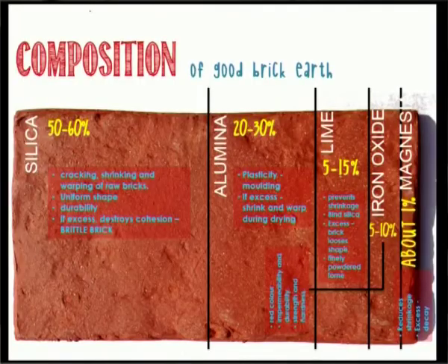If it is in lumps, when you burn the brick, these lumps also get burnt and turn into quicklime. This quicklime is very reactive with water. So when this brick comes in contact with water, the quicklime inside the brick also reacts with water, and this quicklime reacts exothermically, and that will create cracks and compromise the strength of the brick. So always when you are using lime in the brick earth, you should make sure that the lime being used is very finely powdered.